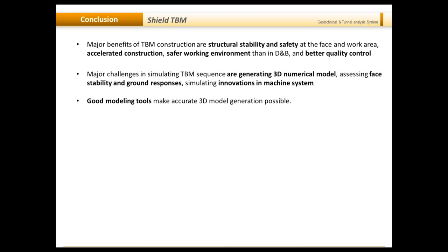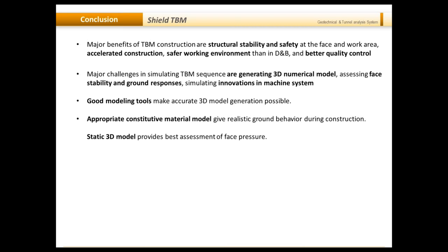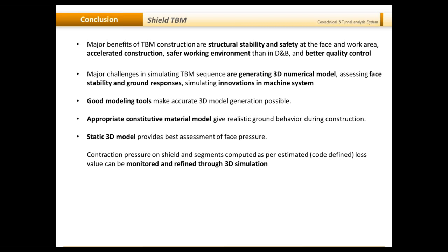Good modeling tools make accurate 3D model generation possible. An appropriately constituted material model would always give you realistic ground behavior during construction. A static 3D model provides the best assessment of face pressure, and contraction pressure on the shield and segments, computed as per the estimated or code-defined loss values, can be monitored and refined through 3D simulation.